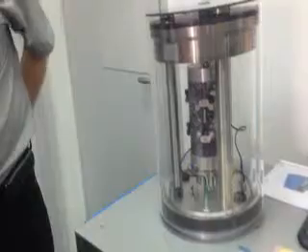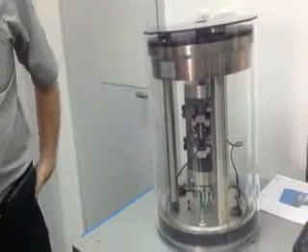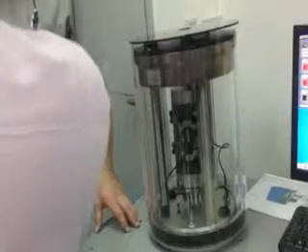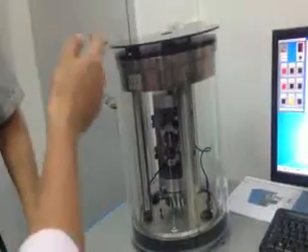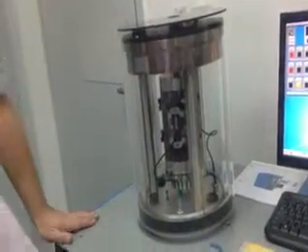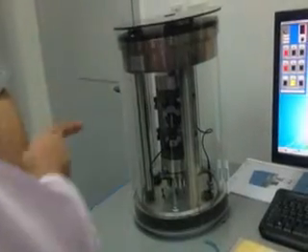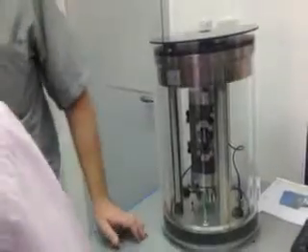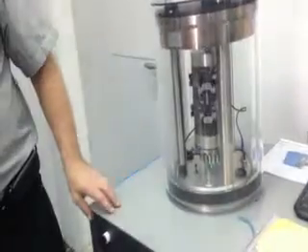For example, we will cut the core sample and put it in the oven to get the test temperature. Then immediately we will get the sample, fix those sensors with glue, and immediately put it back in. Increase the temperature to the condition temperature, whatever the testing requires, 40 or 45 or 50. Whatever it is, keep the same temperature on the sample until the testing finishes.